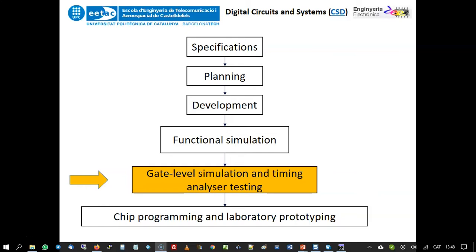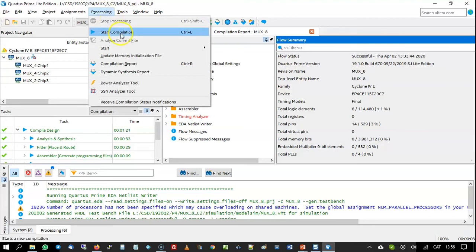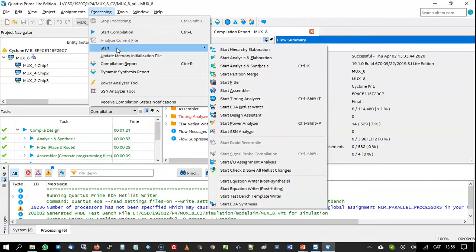All right, so in order to start the gate level simulation, you have to start the processing of the translation of the technology view into a VHDL file. But this technology view in some way is special and has the special extension VHO, right? And you know that this VHO is also associated to the delay file that accompanies the FPGA, which is the target chip of this project.